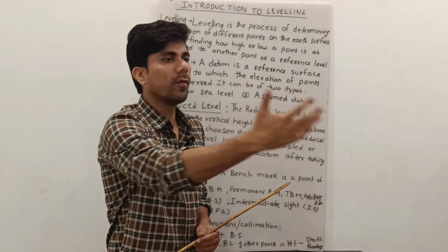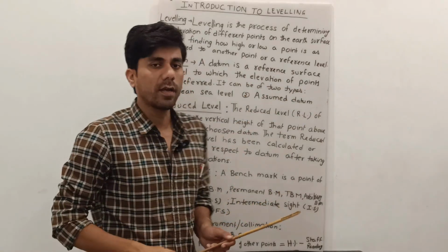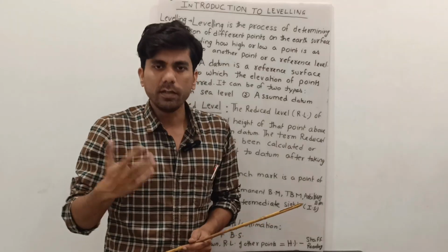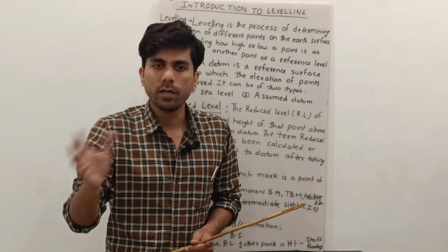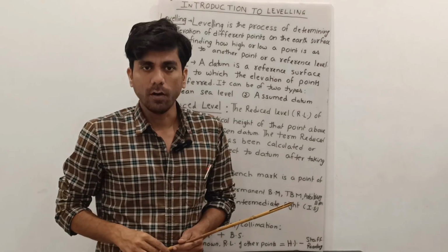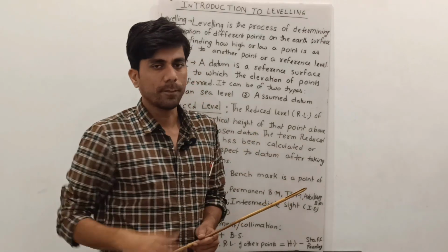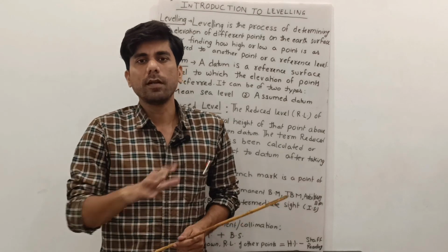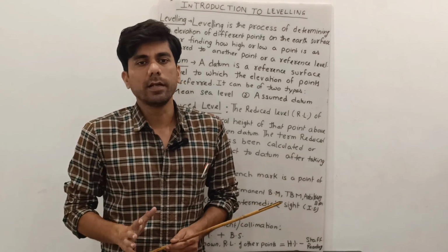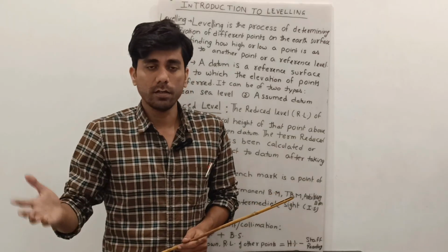Because as we move further in your project, you cannot have the permanent benchmark everywhere. That means the ability of a leveling instrument is like 200 or 250 meters, up to which you can clearly read the observation of a staff. Then after that you have to have a newer benchmark. Also, larger construction projects do not complete in a day. So you have to start your construction another day and yet another day.